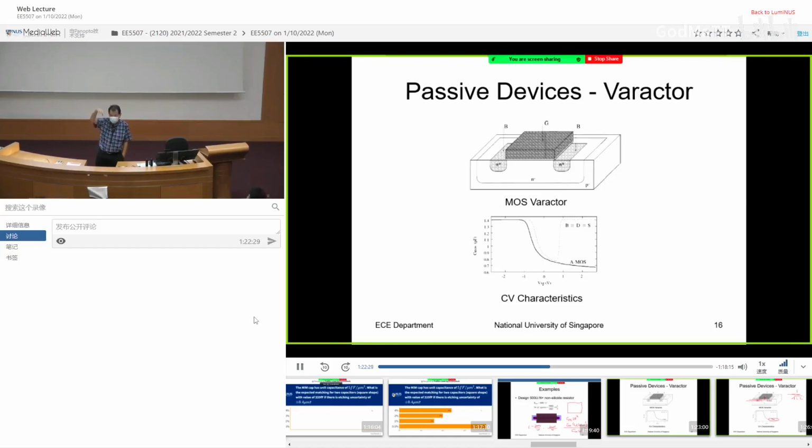So you apply some voltage at the gate. You will try to invert the layer underneath. Once you invert the layer underneath, you can start conducting. So it's a MOS capacitor. But this MOS capacitor device looks very similar to a PMOS device. You can see that the device is being created using an N-well on top of a P substrate. But there is one very key difference.